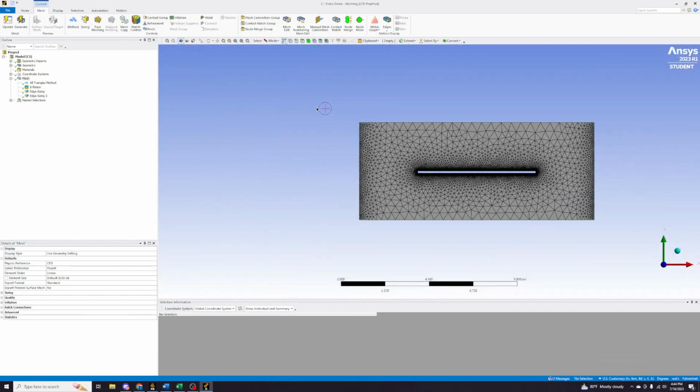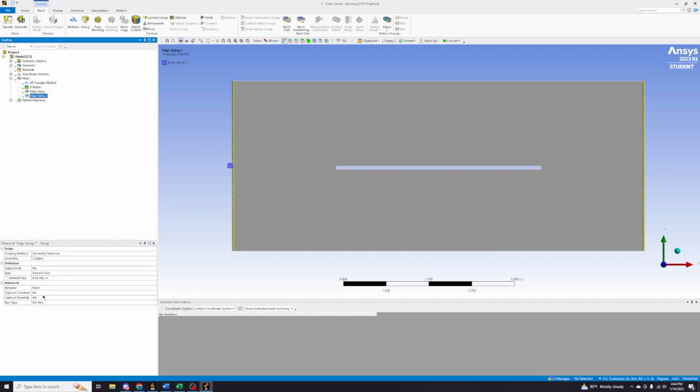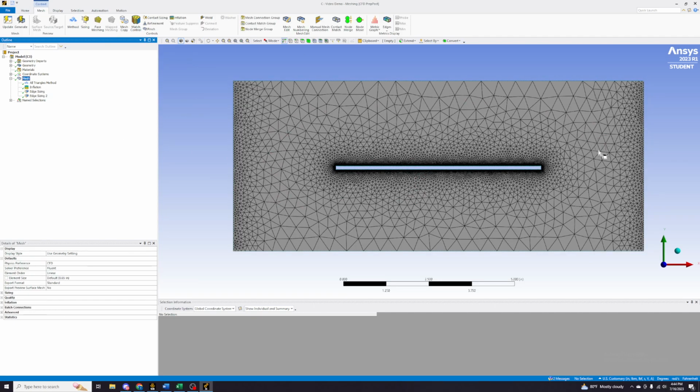And then lastly, I want to make sure that the velocity on the inlet and the outlet are captured nicely on the meshing. So we'll do an edge sizing on the inlet and outlet of 6.5e-2 inches. Same hard behavior. Doesn't really matter, I don't think, that much since it's the wind tunnel portion, but I just keep it consistent. And you'll end up with this meshing here.